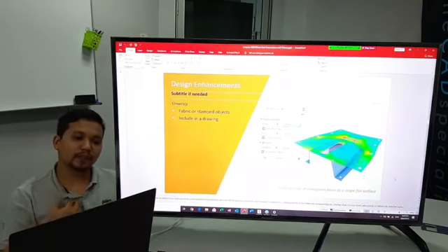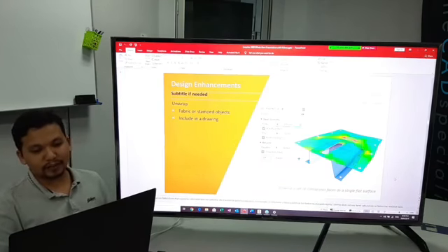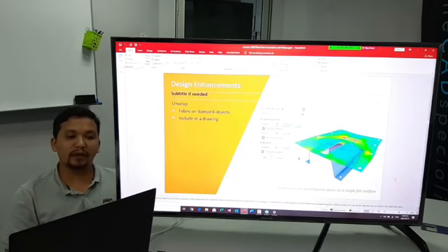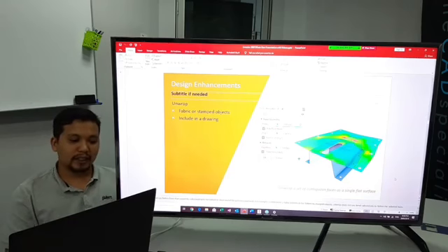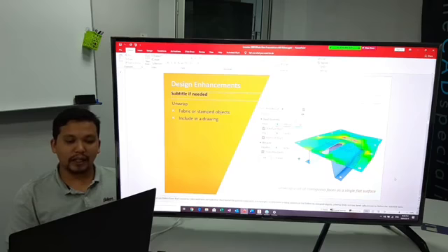Here is another new command to input: you can have the unwrap function inside the 3D model. This new unwrap command can flatten faces that cannot be calculated with the unfold or sheet metal flat pattern command.